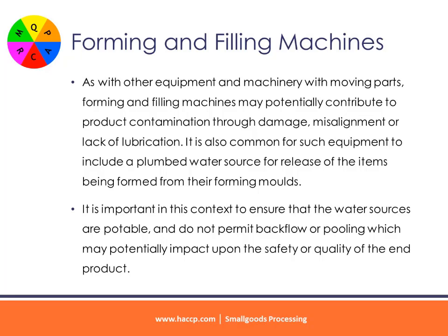Forming and filling machines. As with other equipment and machinery with moving parts, forming and filling machines may potentially contribute to product contamination through damage, misalignment or lack of lubrication. It is also common for such equipment to include a plumbed water source for release of the items being formed from their forming molds. It is important in this context to ensure that the water sources are potable, and do not permit backflow or pooling which may potentially impact upon the safety or quality of the end product.